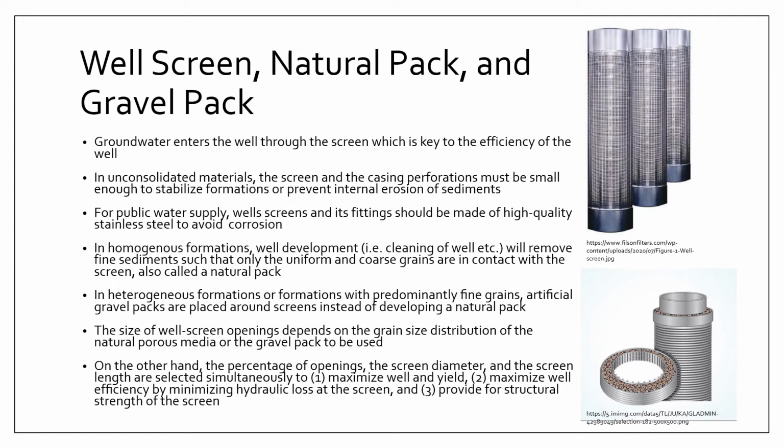Okay, so your gravel packs are placed around your screens, and they are used instead of trying to develop a natural pack. Okay, so a natural pack might not be possible to develop in a formation that has a lot of fines, right?